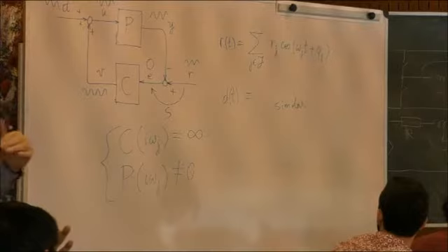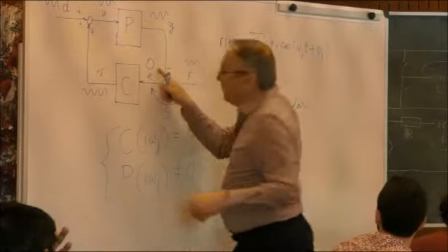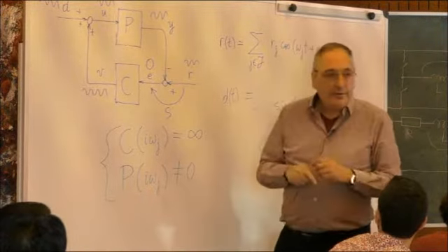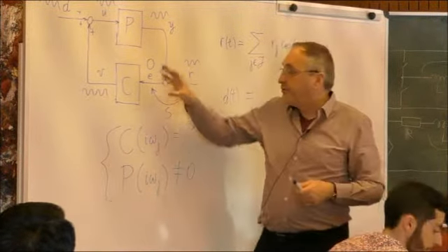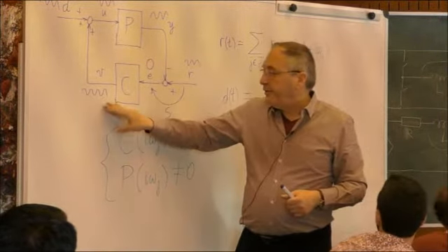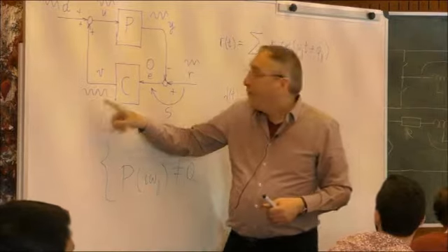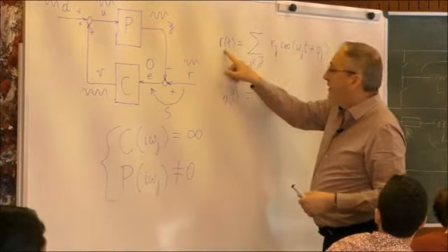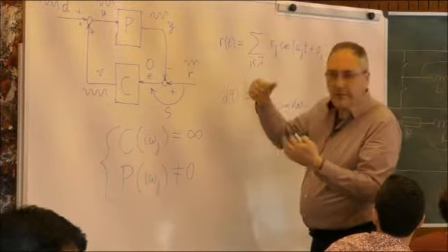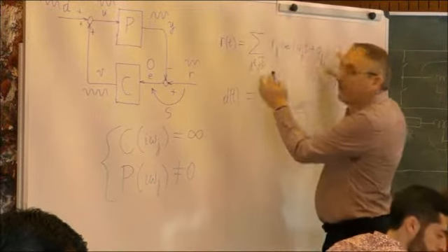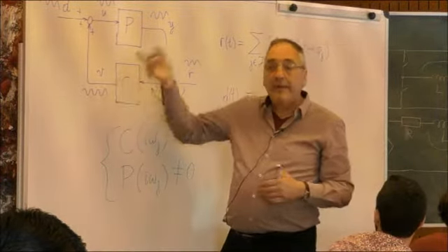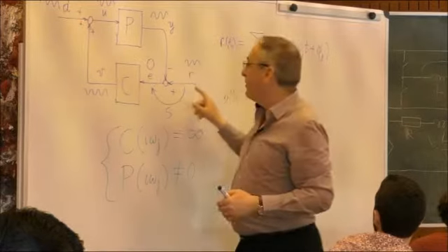It will come back to the steady state situation in which this will be 0, right? But what is important for the name is that the controller receives no input, but it produces a signal which looks exactly like the reference. I mean, it's in the same class of signals. It's not equal to the reference, but it is in the same class, meaning superpositions of sinusoidals. So it will produce a signal of the same class as the disturbance or the reference.